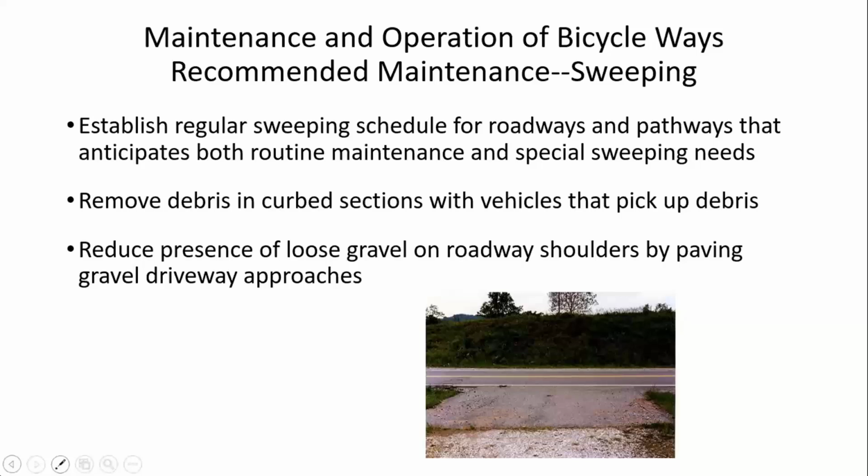And think about another way to reduce the presence of loose stone on the roadway pavement or the roadway shoulder is to maybe require paving of gravel driveway approaches like you see here. That just a few feet of hard surface there, asphalt surface, can go a long way in preventing stones and gravel from reaching the roadway itself.